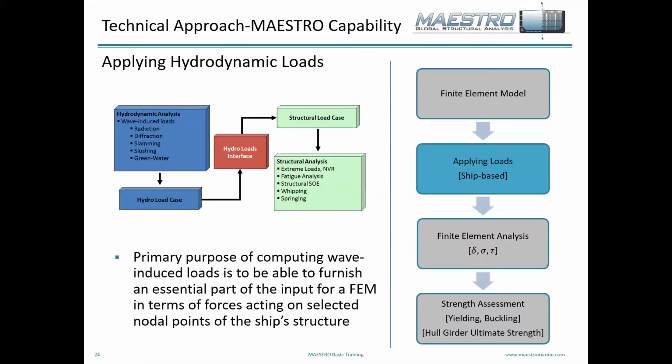When you select a specific load case to be generated, there's a built-in interface which will map all of that information to the structural model. So once you've selected your load case, basically at the click of a button, it will create that structural load case in the FEA model, and then it's just ready to run for the structural analysis.